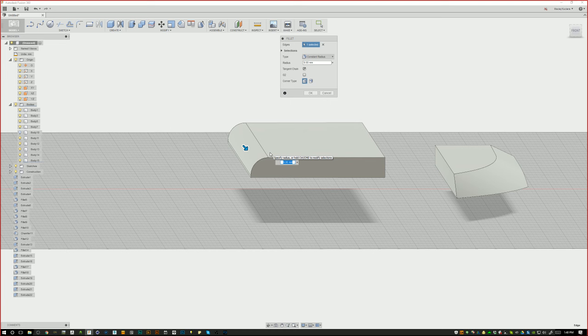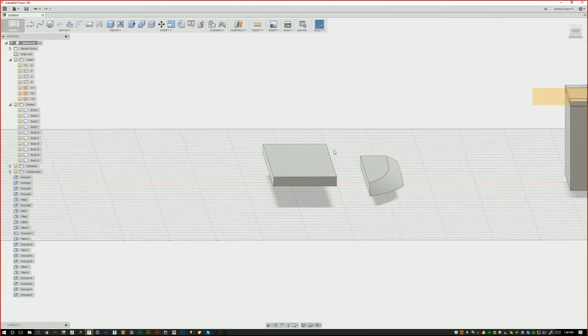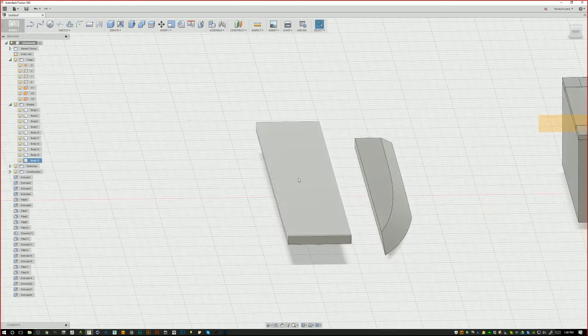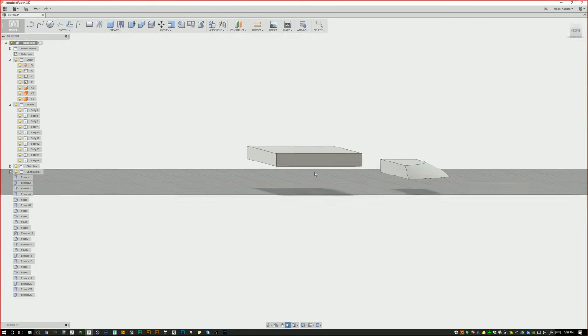So you want to flip it on the inside out, right? Yep, totally. So in this environment, what I would do is actually draw the sketch and then do a cut extrude of what I want. Or if I had another profile that I want to emboss into that edge, I would do a combine feature and Boolean operation to remove it. But today, the easiest way would be to sketch on that front face, draw the shape you want, and then profile cut it out.